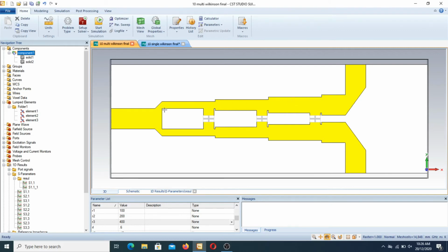It means that the side legs' width is equal to the width of this section, which is used for connection of this resistor. While designing this space, you first have to take an SMD resistor from your market and check the availability of the width. Whether the SMD resistor is 0.8 mm or 0.6 mm, check which length. Then you have to make the length according to the SMDs that you found in the market.